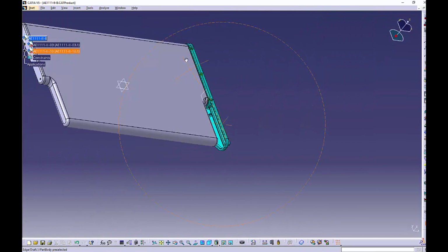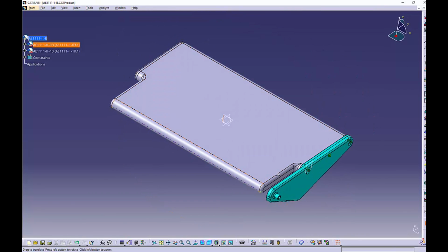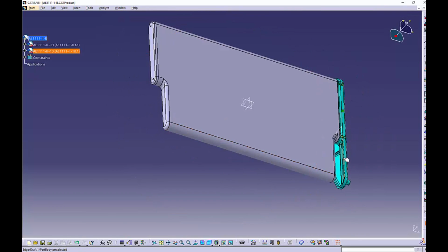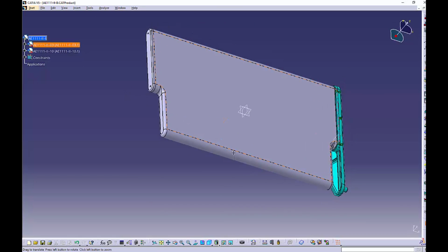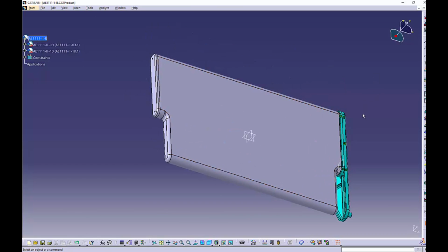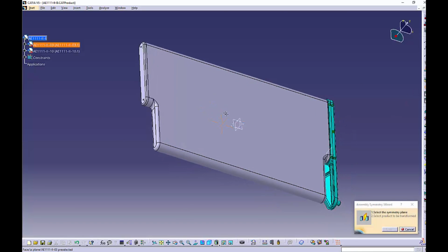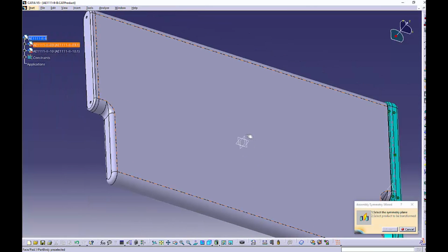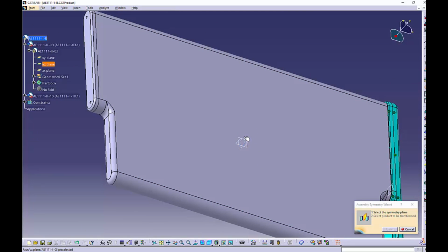It fits perfectly in. Well, now we have it on the one side, we also need it on the other side. So we use the same tool like in the part design that we have done. We want to copy and paste something on the other side. It's called Symmetry. So select from the right tool Symmetry. Select the plane where we want to make the symmetry. I use, let me see, a YZ plane from our stairs. So part number 3, the YZ plane.